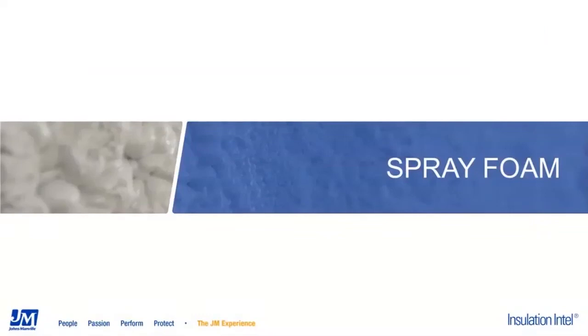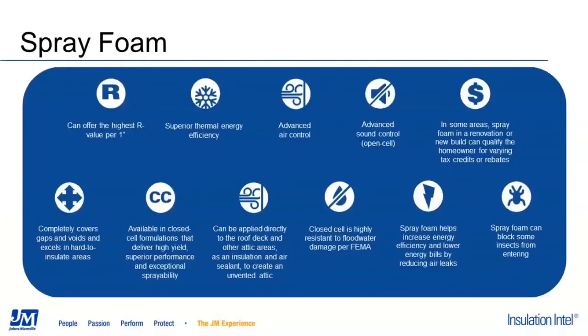Next, I'm going to talk about our spray foam product offering. In Canada, we offer a 2-pound closed cell spray foam product. There are many benefits of using spray foam to meet your insulation needs. A few of those benefits are the highest R value per inch of any insulation product, which provides superior thermal energy efficiency in your building.